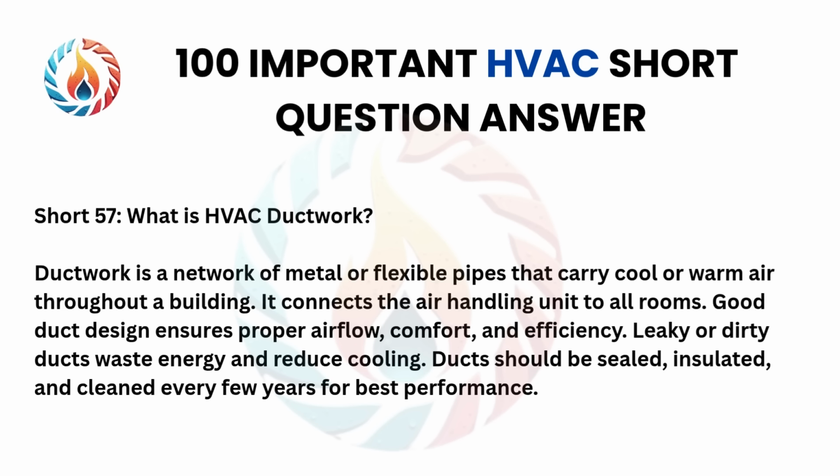Short 57. What is HVAC ductwork? Ductwork is a network of metal or flexible pipes that carry cool or warm air throughout a building. It connects the air handling unit to all rooms. Good duct design ensures proper airflow, comfort, and efficiency. Leaky or dirty ducts waste energy and reduce cooling. Ducts should be sealed, insulated, and cleaned every few years for best performance.